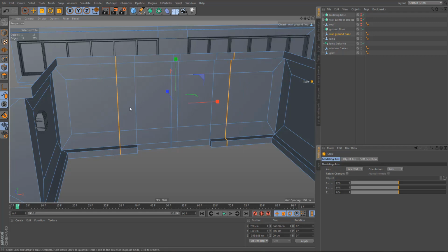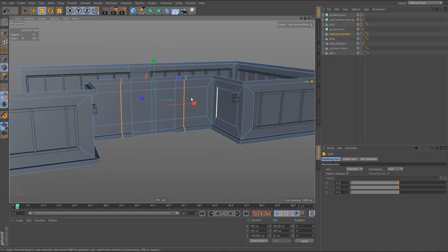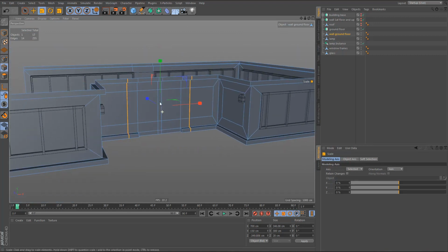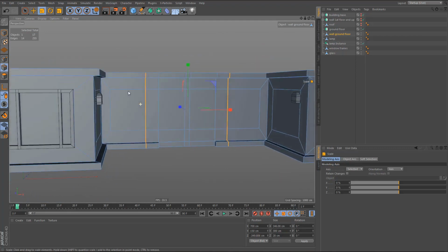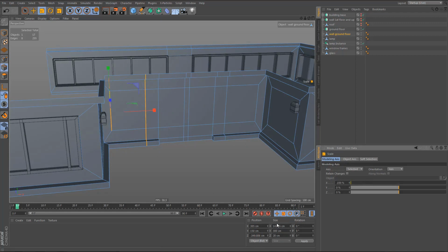I'll leave a little bit of room between the door and the windows, because we could put a lamp to the right and to the left of these doors. And let's see, we could give these an even width. Let's do 140. I'll just move the x-axis over here, and I'll change the width of this window to 140.